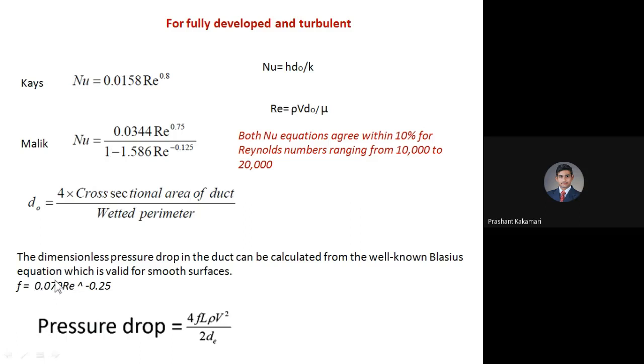So now, coming to the other factor, for example pressure drop. This is very important for the air collectors, not for the liquid flat plate collectors. In the air heaters, if the pressure drop in the flow is very high or very low, the energy required to generate the flow of hot air increases, which is difficult. So it should be in between; it should be minimum, but not very low either. If the pressure drop is very low, then the flow is also not possible.